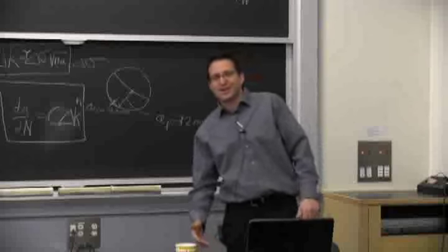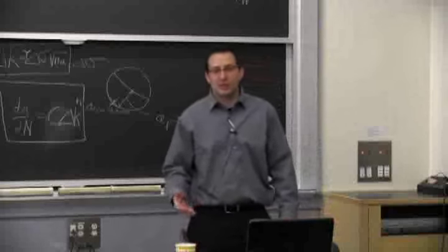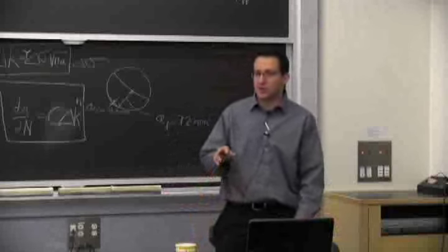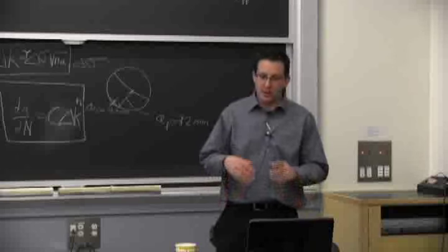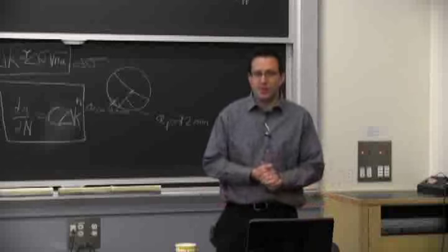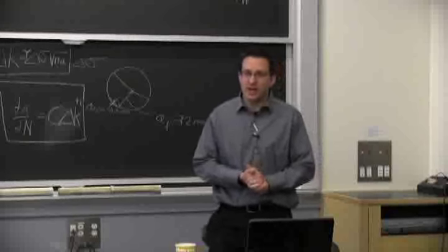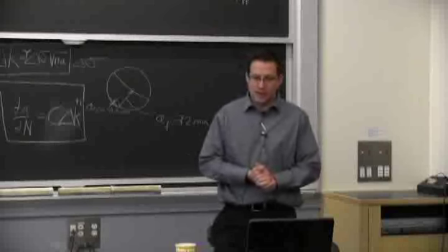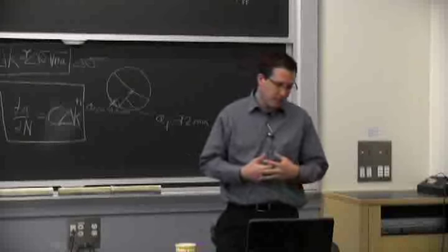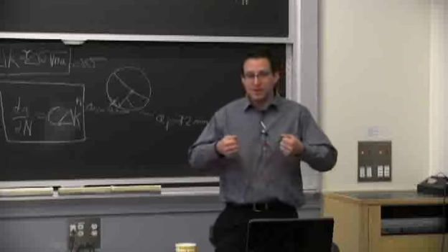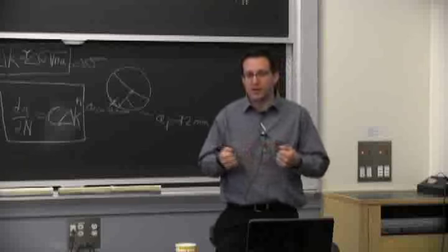So I think it's a great demonstration that everything we talked about so far, as far as really having a plastic zone, because we have a stress intensity and the material will flow, that's a demonstration of that. And you can think that if you have a lot of ductility in your material, it will require more energy to blunt that crack tip and make it move back and forth.